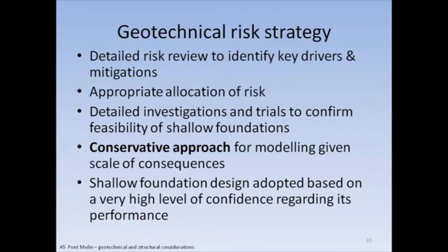So very early on, and this is to the credit of the Welsh Assembly Government, they were very keen to review those risks in detail and to develop a proper strategy for them and a proper allocation of those risks. They promoted the approach that we adopted, which was further detailed investigations and trials at some expense to look at the feasibility of shallow foundations, and as part of that, because of the level of risk, a conservative approach was adopted. Ultimately, we were able to go forward with shallow foundations as a solution because of the confidence we had based on the information that we'd obtained and the approach that we took.